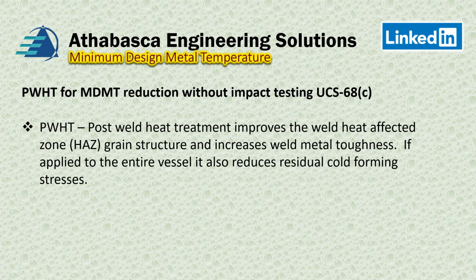And so this is if the entire vessel, it also reduces the residual cold forming stresses in the material. So that's like when something's been cast, or you have a welded assembly, and then the welding's hot, and then it shrinks, and then it puts stress into the part. And so this is a great way to remove that.